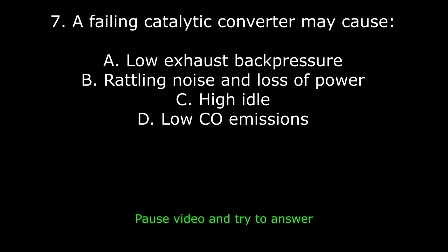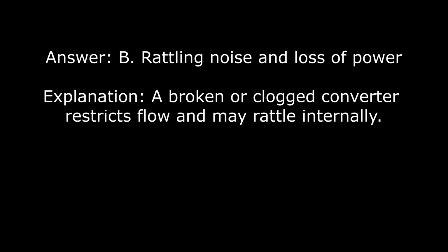7. A failing catalytic converter may cause A. Low exhaust back pressure. B. Rattling noise and loss of power. C. High idle. D. Low CO emissions. Answer? B. Rattling noise and loss of power. Explanation. A broken or clogged converter restricts flow and may rattle internally.